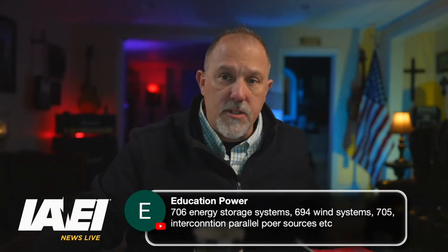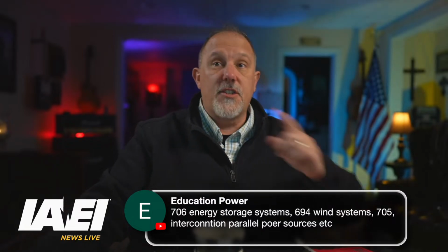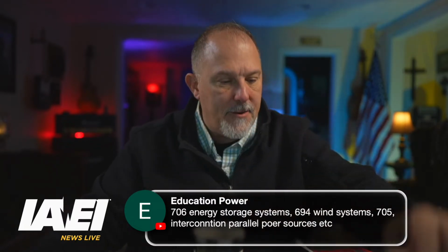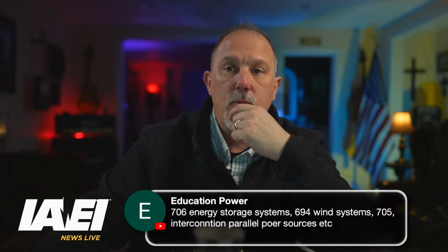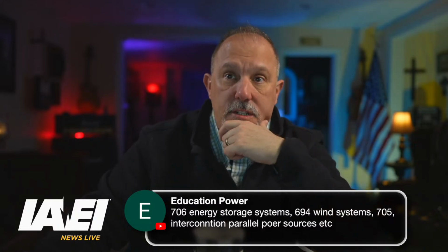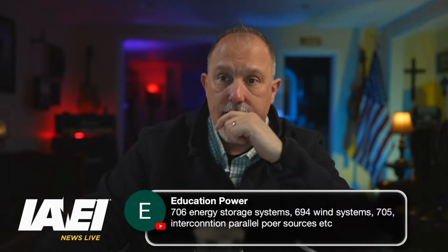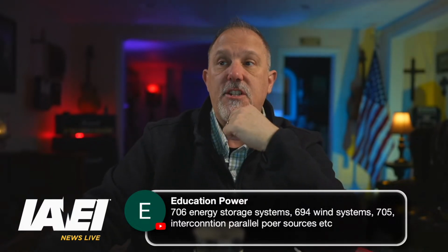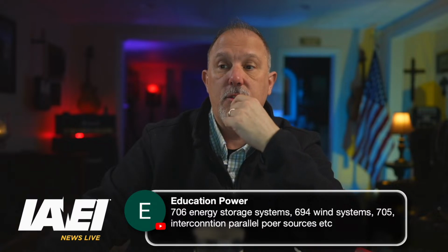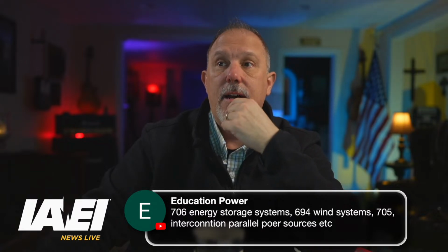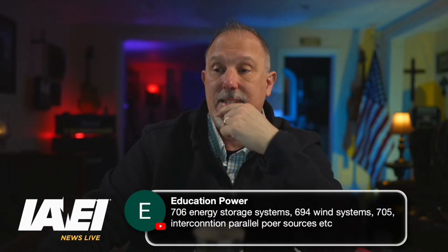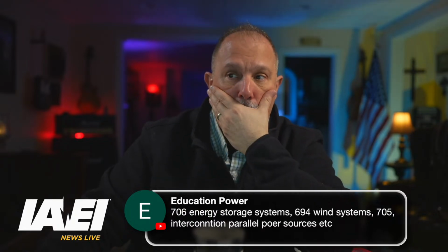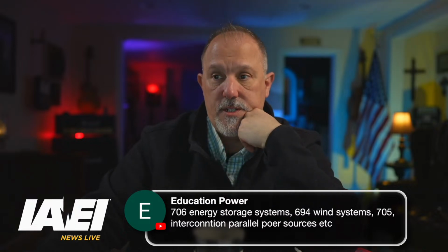706. Oh, Article 706. Right. So 480 is batteries, but to your point, Robert, Article 706 will be your energy storage systems. Where's 706? Energy storage systems talk about the required for a. They'll say that the energy storage system has to be listed as an energy storage system.